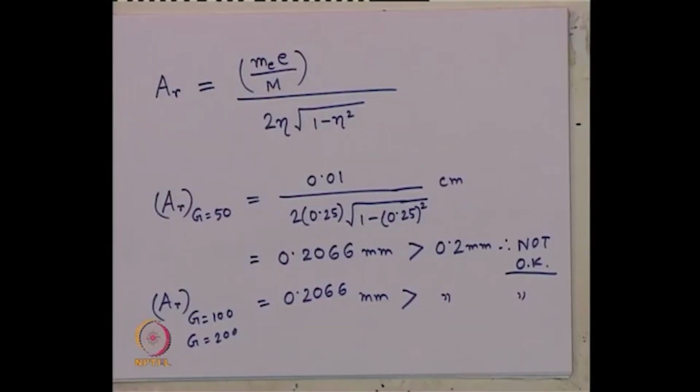So, for rotating mass type, the same block type of foundation in all the three cases of soil, at operating frequency they are perfectly fine, because the displacement amplitudes are within permissible range. However, at resonance frequency it is not okay for all the three different types of soil. So, with this we have completed only the analysis for vertical mode of vibration. Now, let us go for next mode of vibration, which is sliding mode of vibration.